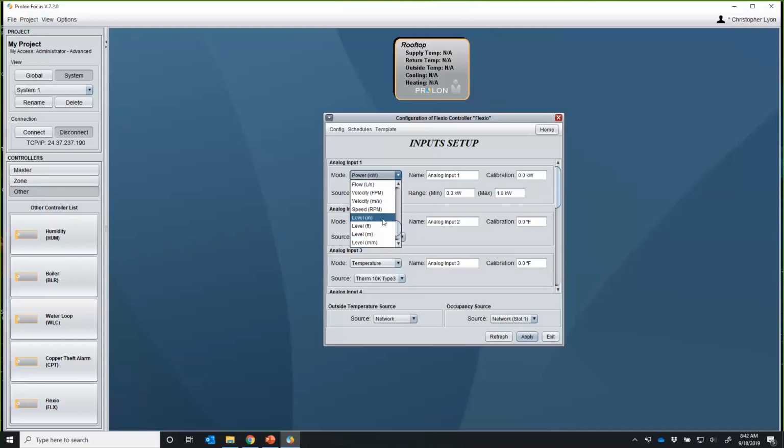How about this? Level, transducer, think tank level sensors. You put the little transducer at the bottom of the tank, and it's going to tell you how many feet of liquid is in this tank based on the weight of it. So you can use this for an autofill or a pump to ramp that pump up and down. Percentage